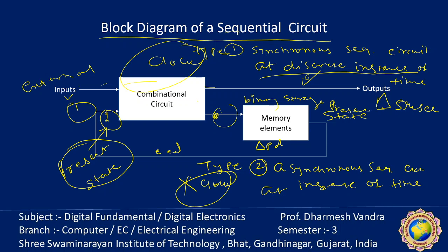In practice, normally the internal propagation delay of a logic gate is of sufficient duration to provide the needed delay, so that a physical time delay unit may be unnecessary. Remember that in gate type asynchronous circuit design, the memory element consists of a logic gate whose propagation delay provides the required memory. Thus, an asynchronous sequential circuit may be regarded as a combinational circuit with feedback. In simple words, combinational plus feedback.